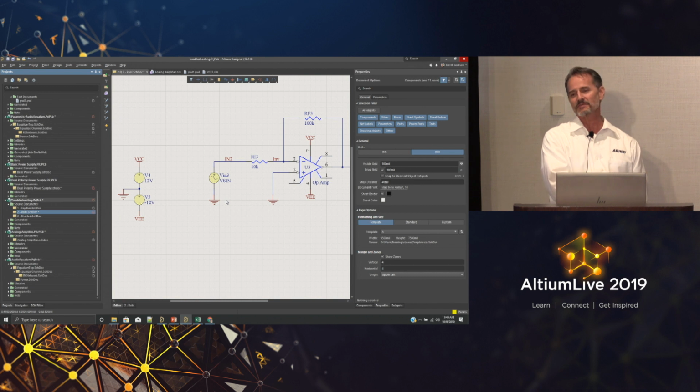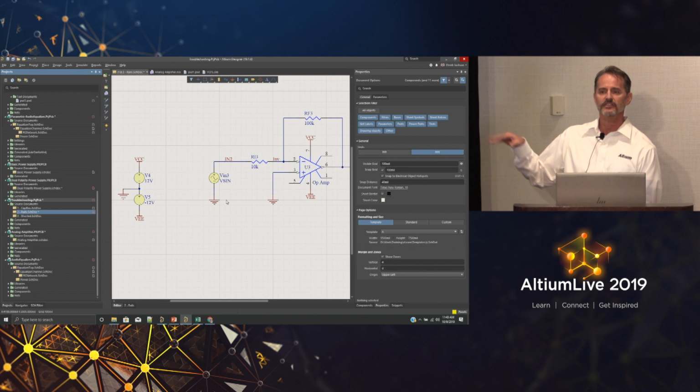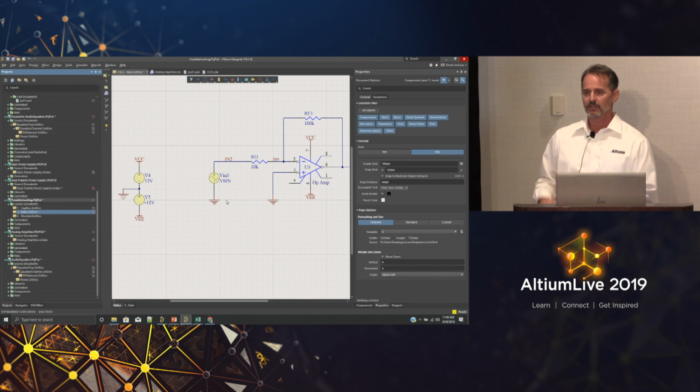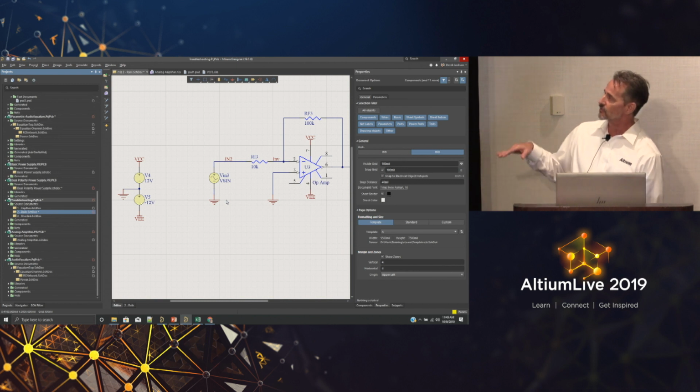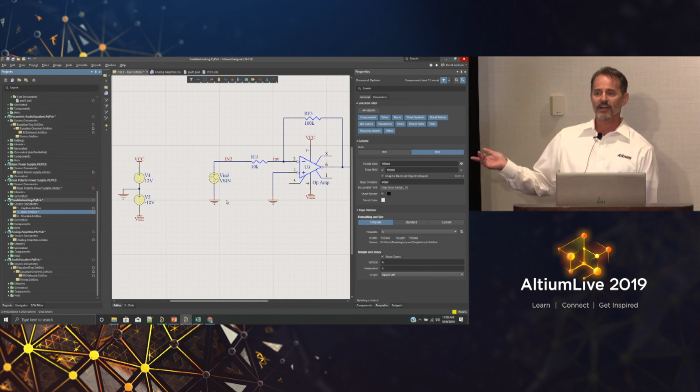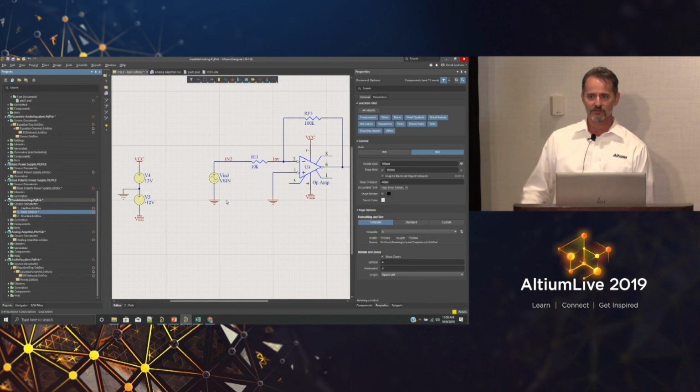Maybe down the road we can partner with LTspice. But right now, you can export out a netlist. You clean it up, because sometimes it'll complain about some of the options, you save it out with the .cir extension, and you load it in LTspice. You can run our generated netlist right out of it.